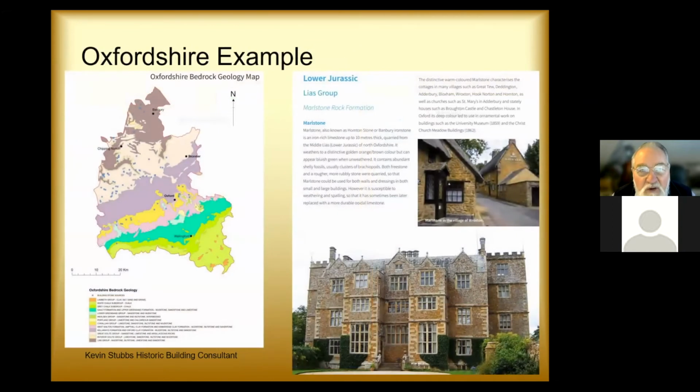And I just bring up here a page or two from the Oxfordshire Atlas, and it shows the various geological beds of material, and also pinpoints where the quarries were exploiting these materials, and then examples of the typical way the stone was used, either as a freestone with stone ashlar, quoins and window and door surrounds, etc.